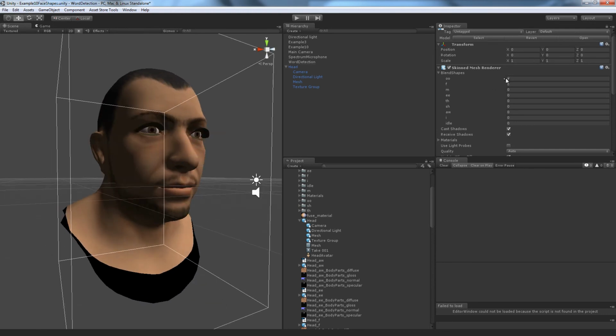Now these are blend shapes, so I can use the blend shape sliders to turn these on and off. So 100 being 100%, you can do 1,000, 200. I guess it's clamped, but the inspector doesn't really clamp it. So I can go above 100 and nothing happens, or if it's negative, it essentially counts it as 0. Cool. So you can affect these in the inspector, or do it through script by using SetBlendShapeWeight in the API.